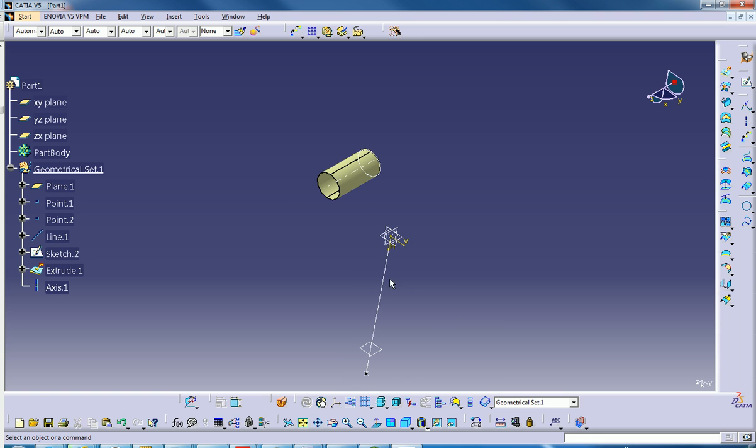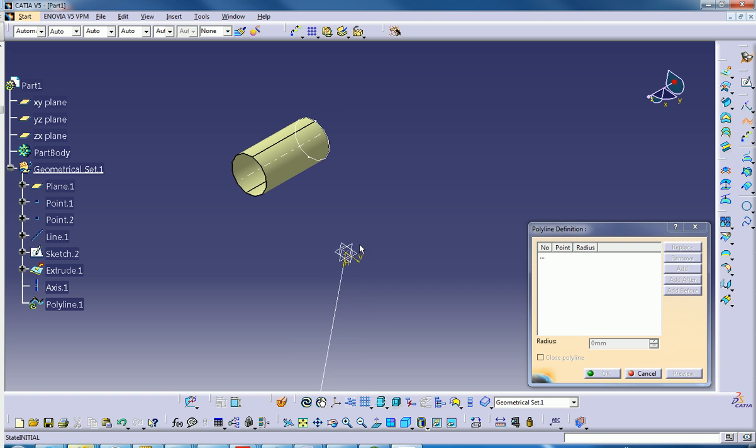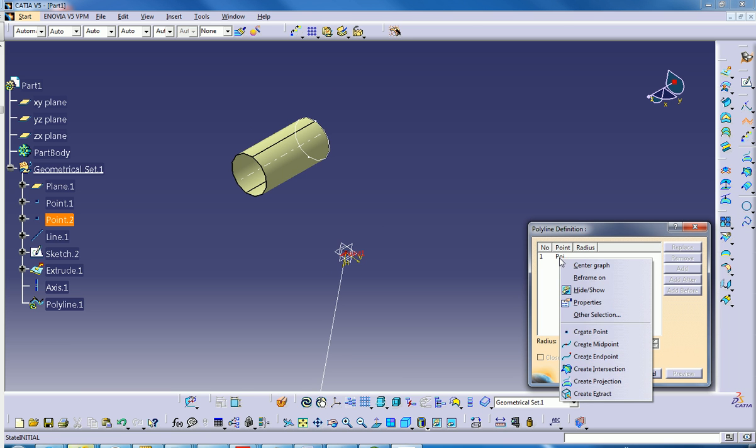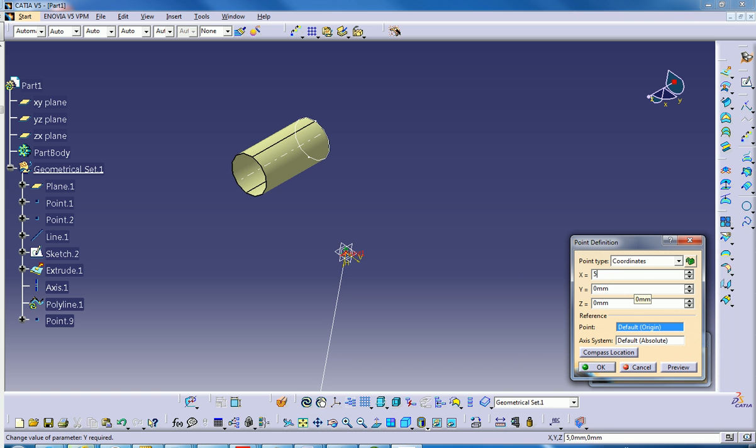So that's one point. Another interesting tool that we can deal with is the polyline tool. Right within here, you'll see the polyline. So I can pick on it, and be able to connect points, like connecting dots really. What's nice is that I can click on existing points, or I can right click and build points on the fly. So I can say I know that my next point has to be 50, maybe 40, and maybe 90 over here.